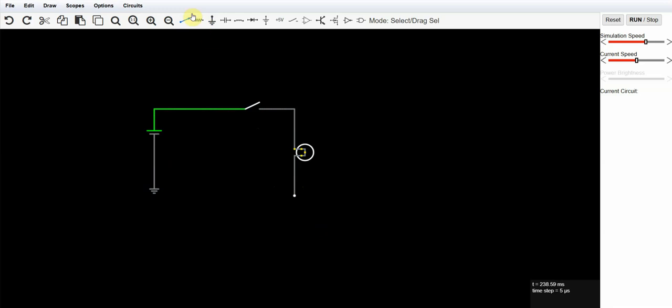I'm going to bring a wire in here. I'm going to connect from this dot to that dot. Notice, see the little red dot there? The red dot tells me that it's not going to work if I let go of the mouse button. So I have to go to a blue dot, like right there. My mistake earlier was I thought that I could just drop this wire anywhere and it would pick it up, but it doesn't. You have to drop it on a dot, a node, right? So like that should work.